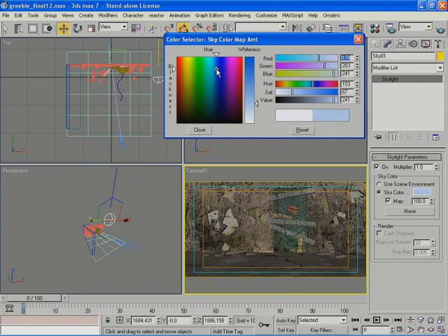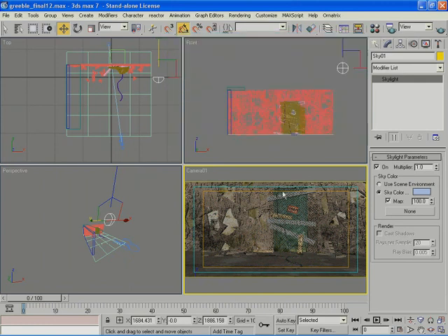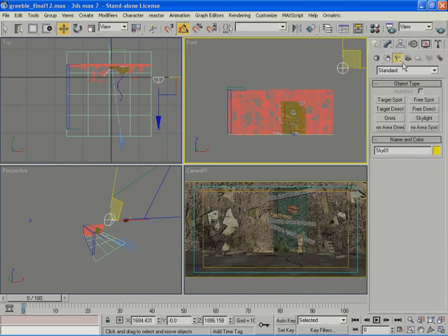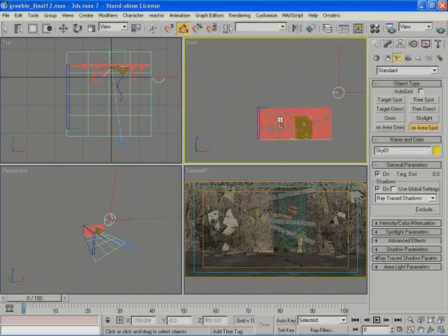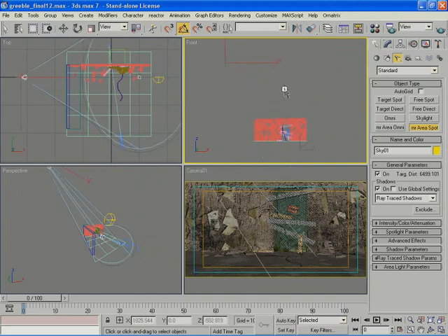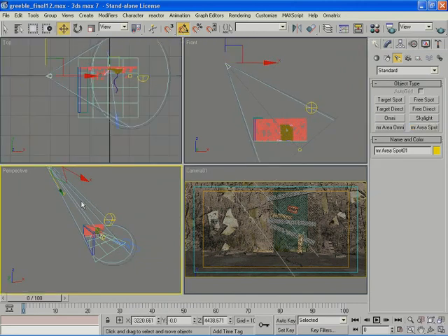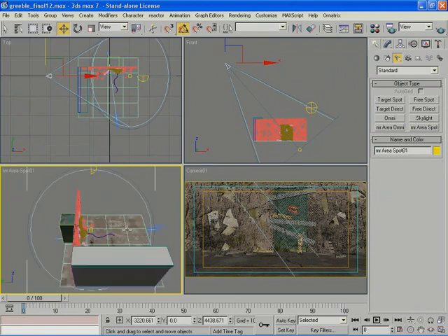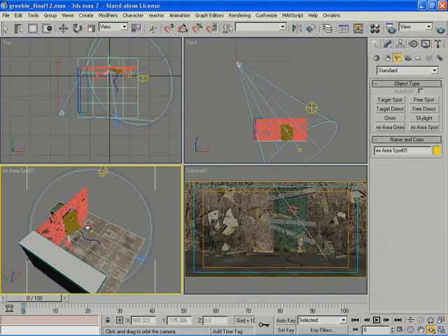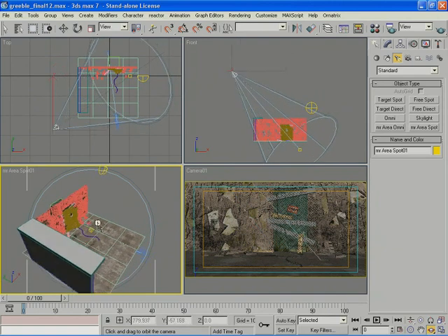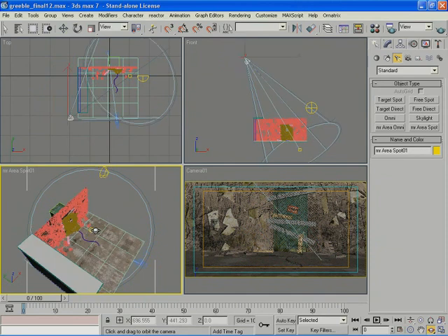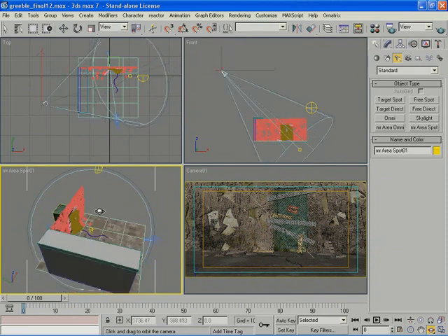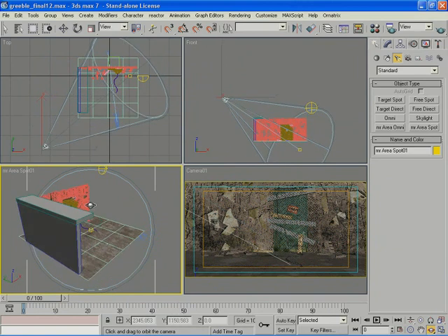Now I'm going to right click here and choose set view to selected light so that this view goes to the light. I'm going to uncheck angle snap, press V and change the view so that I get the light direction that I'm looking for. So basically I want it to look a bit like this. I want the shadow to pass through the door here. So I make sure that the whole scene is within the light range, and I fix my view like so. So let's keep it at this now.